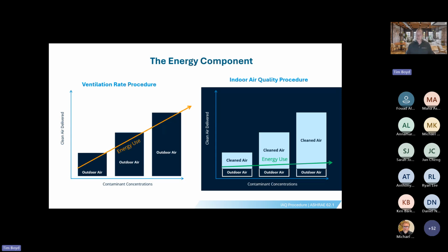In the indoor air quality procedure, you would design your outdoor air such that you're managing to the pressurization of that building, right? That's always fundamentally key. You want to positively pressurize your building. Then you want to add in anything that you might require for exfiltration needs, whether you're turning on an exhaust fan for a bathroom or a kitchen. Those are all important to include in outdoor air.